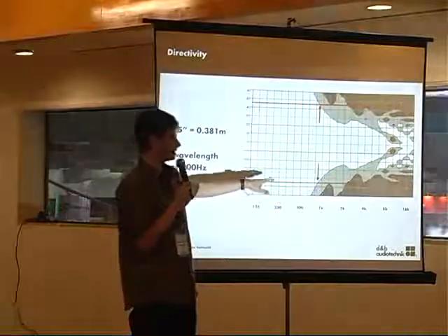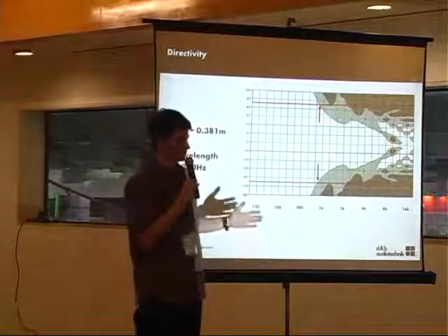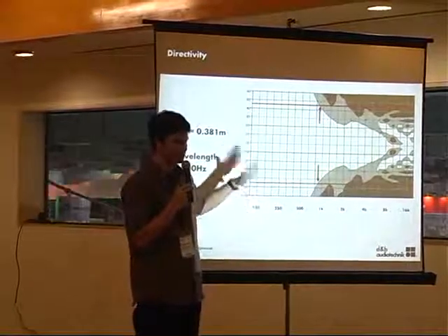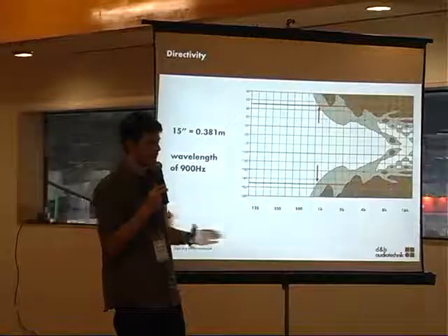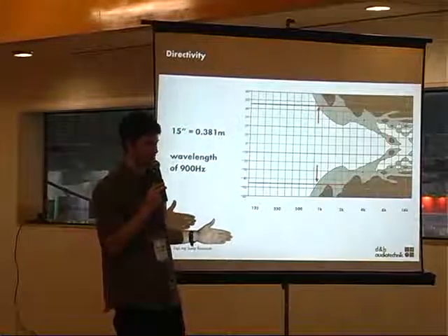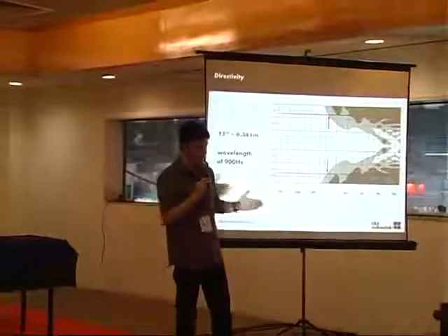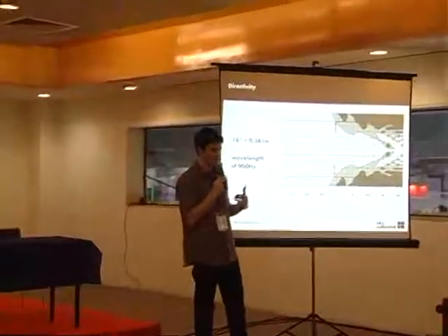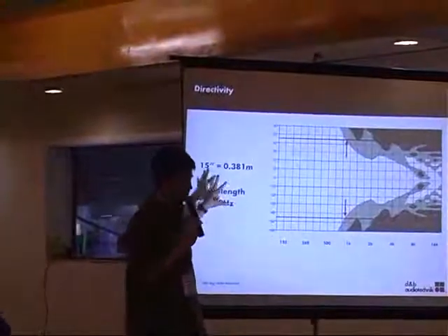As soon as we reach that frequency, we will find with every box imaginable that at this frequency it will have roughly plus minus 45 or 90 degrees of total dispersion regarding its minus 6 dB angle. And we know immediately if we go higher in frequency, the coverage can be more narrow. If we go lower in frequency, the coverage will be more wide. This is just what happens with a single source.